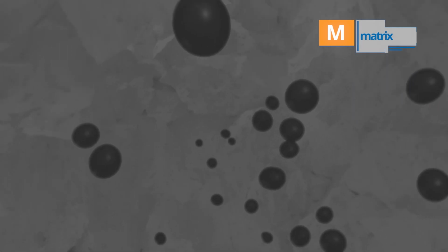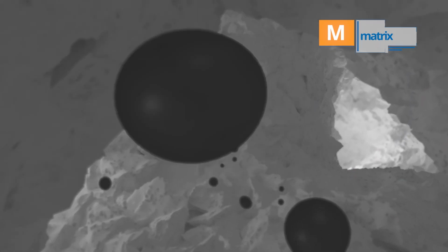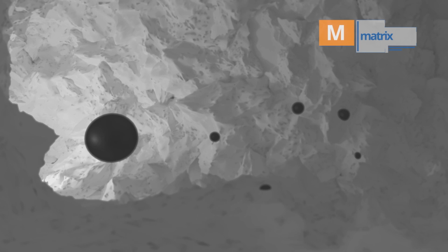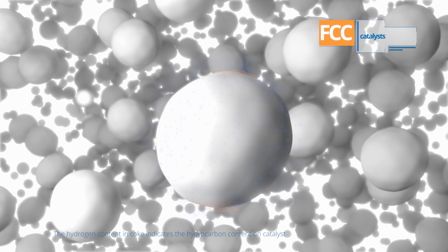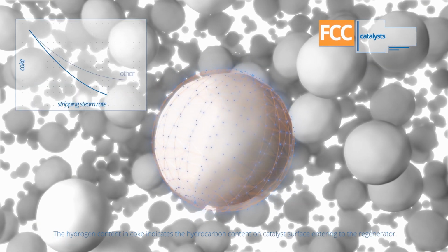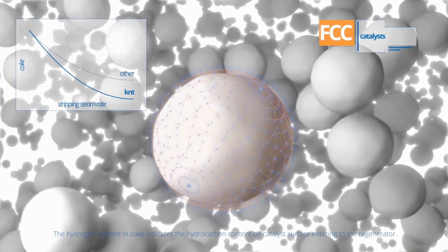The size of heavy hydrocarbon molecules is 30 to 50 angstroms. Therefore, the active sites of the zeolite cell are not accessible for cracking. Matrix with an optimal mesoporous structure allows for both the preliminary cracking of molecules with a high molecular weight to a smaller size, and the diffusion of feed molecules to the zeolite active sites, which increases the cracking efficiency of the bottom feed. The optimal pore distribution provides for not only high conversion, but also more efficient product stripping from